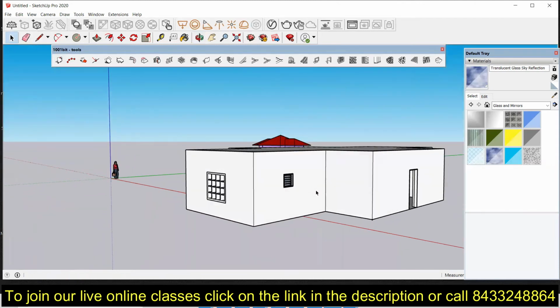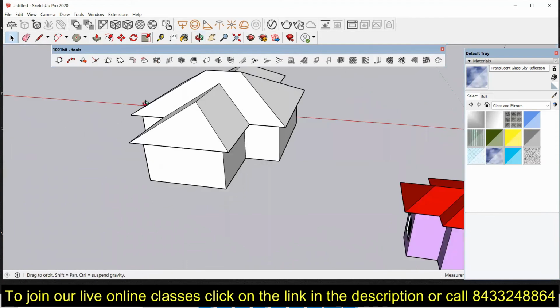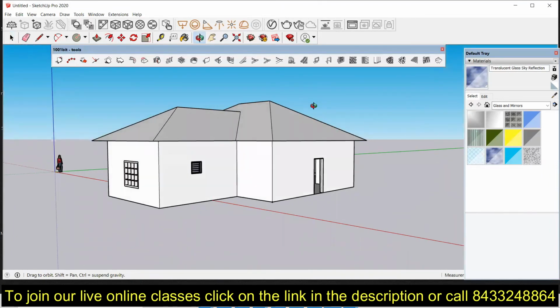this is fine, but what if you want to get a roof like this? You would have to draw a lot of lines and then start working on it. But if you are using this extension that automatically creates a hip roof from a face, then it will be very easy for you. So just select this one and click on this one. Then you will have to set the heights. Okay, so the roof pitch will be 30, so that is okay. Roof overhang is 2 feet, so that is also okay. Now click on create roof. So now you can see it is very easily creating the roof over here. Okay, so if you are using the extension, then obviously your modeling will be very easy.